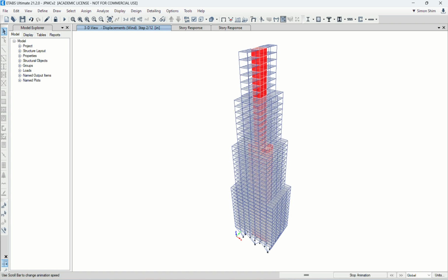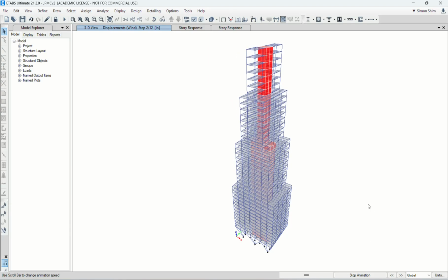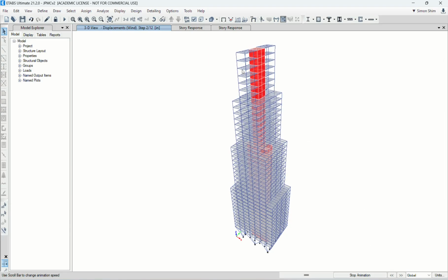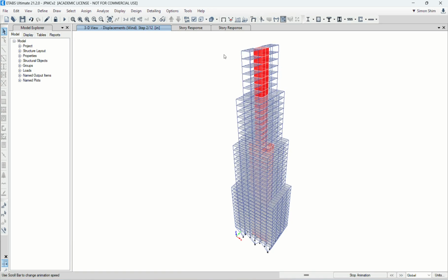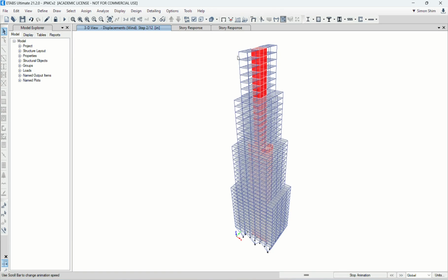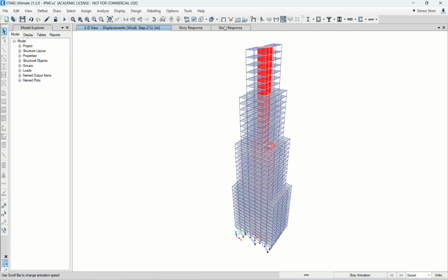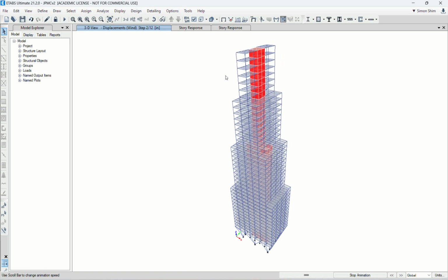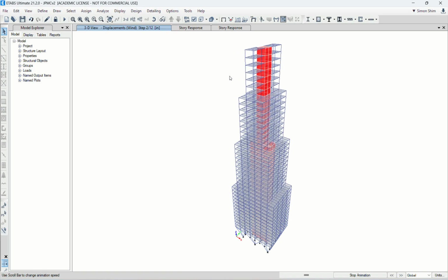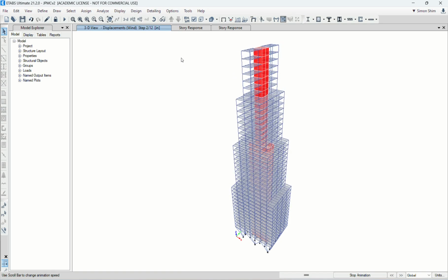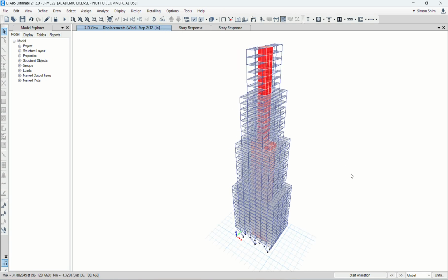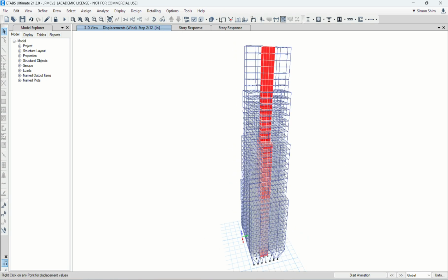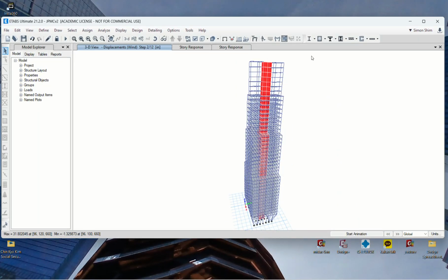If you may have some geometry disconnected member, you will see the building members overlapping each other. But I want you to just check the displacements, make sure everything is connected and working globally. So you should at least always double check your model before you move on to the next step.